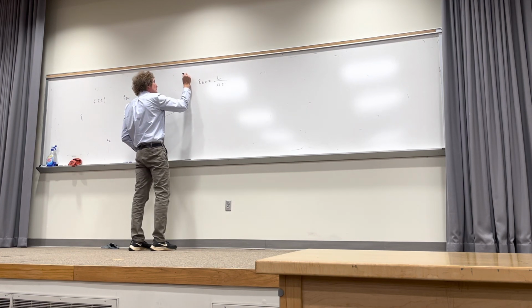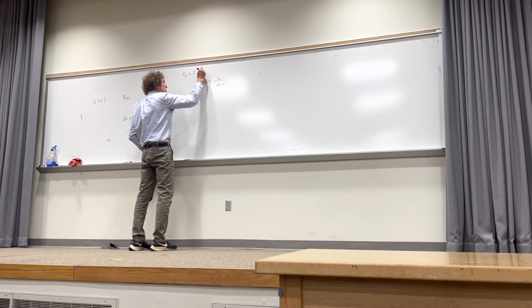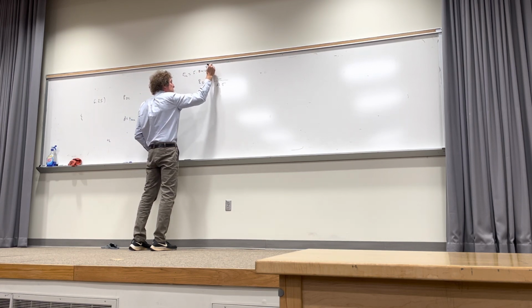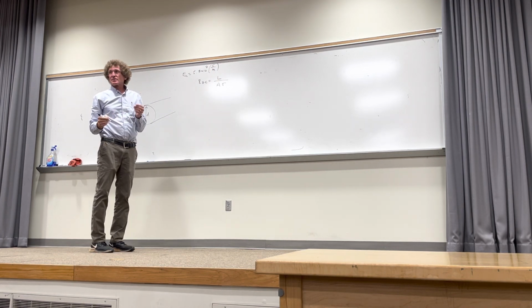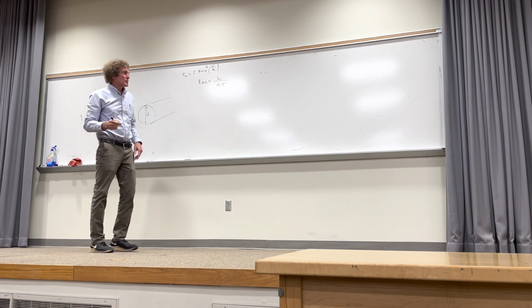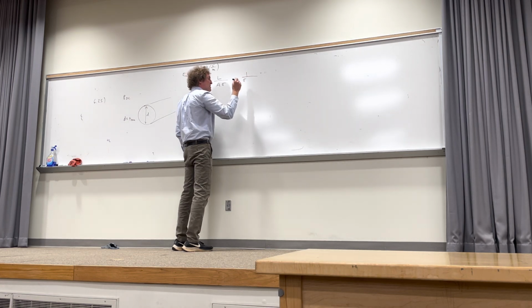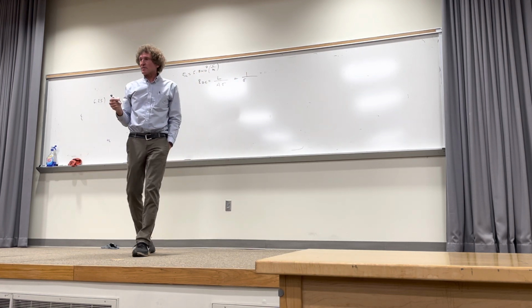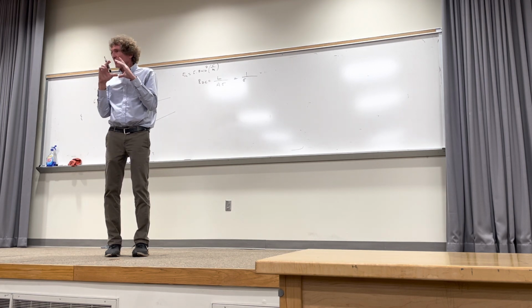Now sigma for copper is 5.8 times 10 to the 7th, and the units are either Siemens per meter or 1/ohm meters. Now that's resistance for any given length. If it's per meter, it'll just be 1 over sigma times the cross-sectional area. If it's a wire with a circular cross-section, it's just pi a squared if a was the radius, or pi d squared over 4 if it's diameter. Follow?